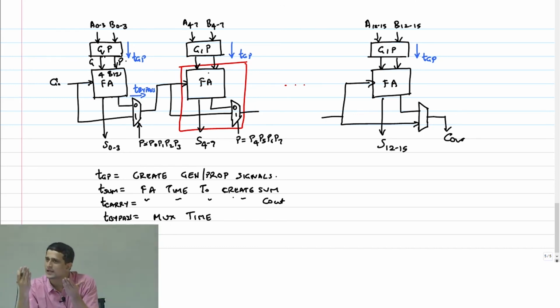Right? It's the same thing as the ripple adder. If my last stage is in generate mode, then there's no question of that being the worst case delay. Carry out is ready immediately. So it has to be somewhere earlier. How much earlier? We said it has to go all the way to the first bit. So I'm asking similar questions here. Can any bit in between 0 to this thing be in generate mode?